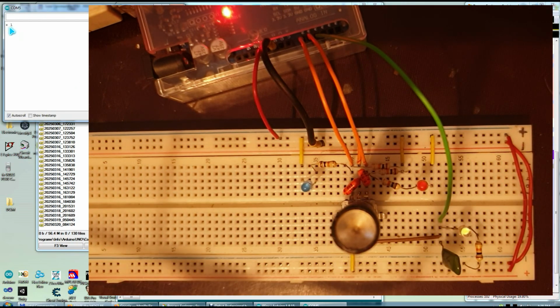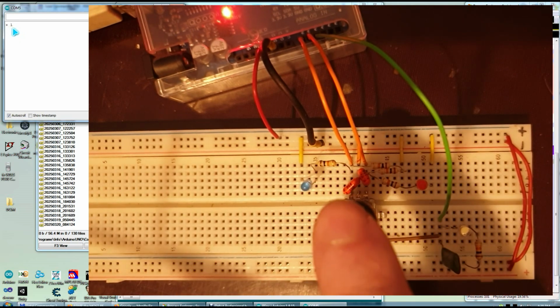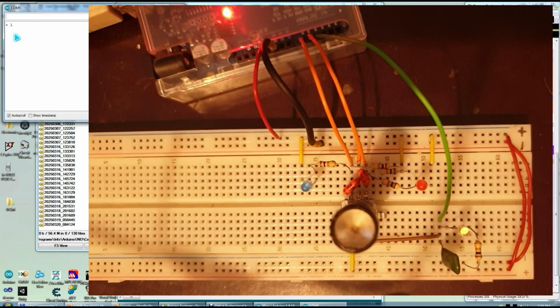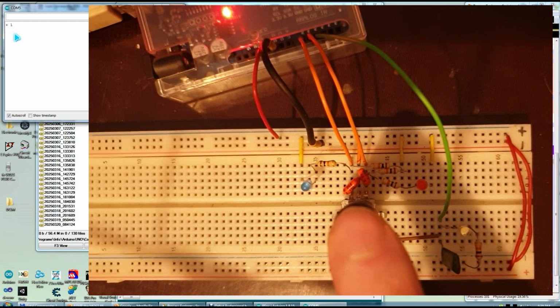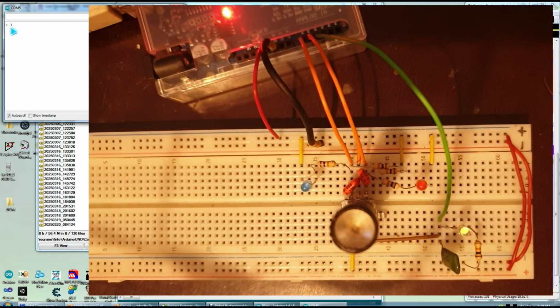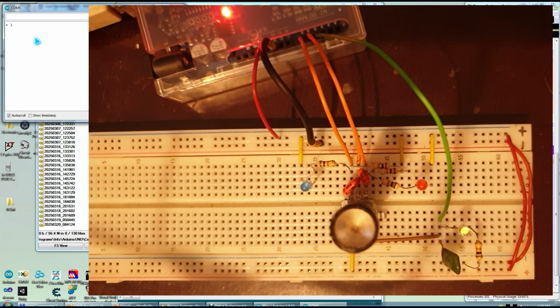We are having only one number there showing, with this code, this binary Gray code that you've seen in those two LEDs. A quadrature Rotary encoder creates 4 steps as a Gray code, and you've seen it with the help of those two LEDs. My program is counting only one time, decoding those 4 bits of binary: the first is on, the second is on, then the first is off, then the second is off. This is the sequence. The whole sequence of binary is decoded by my code and correctly outputted as one single number, not multiple numbers or with errors.